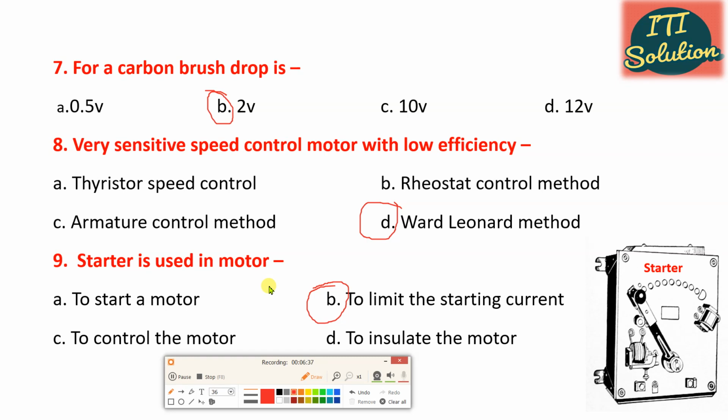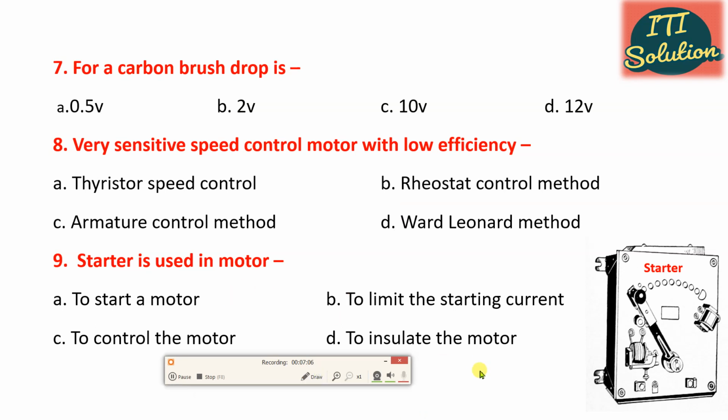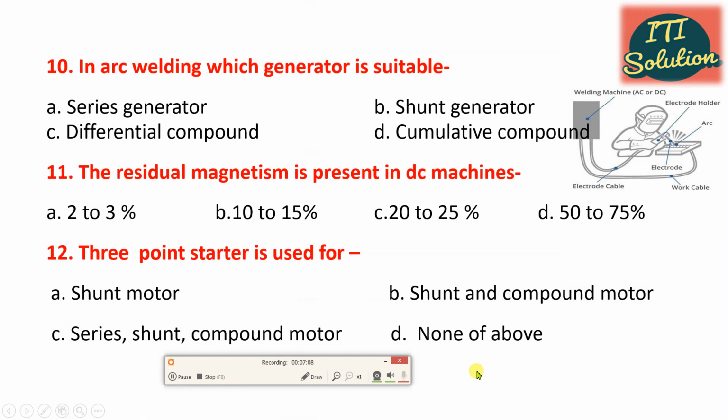This heavy current may result in burning the armature due to excessive heat effect, and so damaging the commutator and brushes due to heavy sparking. Excessive voltage drop occurs. In order to avoid this, starter resistance is inserted in series with the motor. Okay, clear?